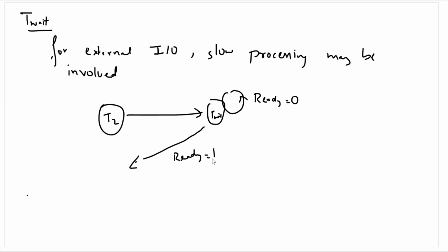Slow processing I/O devices or memories can result in the microprocessor waiting until the data bus basically reads the data completely. The microprocessor enters the wait state, and the number of cycles depends upon how slow the I/O device is.